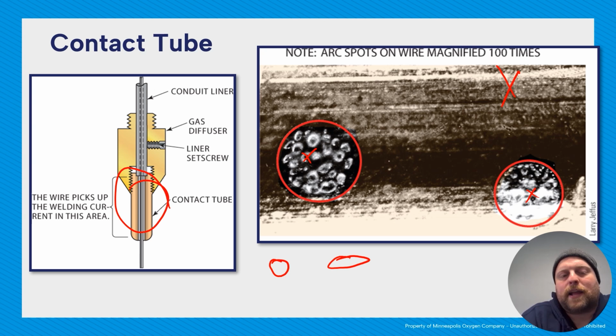Something to think about and watch out for, you might not know, but the actual filler for GMAW has in particular what's called cast and helix. So it's wound onto the spools in a very particular way. When you're loading and unloading, if you're not making sure it doesn't become unwound, what can happen is, because there is some tension in that, it can become unwound a little bit. When it becomes unwound, it can lose the cast and the helix, or basically the way it was wrapped.